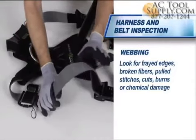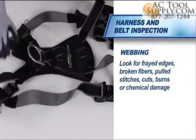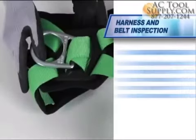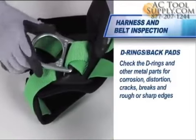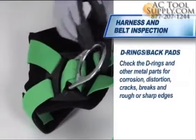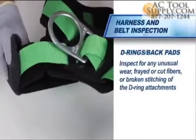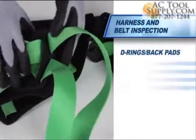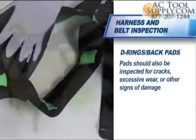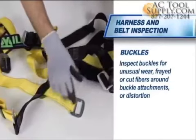Follow this procedure for the entire length of the webbing on both sides, looking for frayed edges, broken fibers, pulled stitches, cuts, burns, or chemical damage. Check the D-rings and other metal parts for corrosion, distortion, cracks, breaks, and rough or sharp edges. The D-ring should pivot freely. Inspect for any unusual wear, frayed or cut fibers, or broken stitching of the D-ring attachments. Pads should also be inspected for cracks, excessive wear, or other signs of damage. Inspect buckles for unusual wear or distortion, fibers around buckle attachments, or distortion.